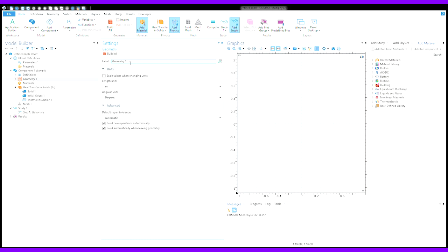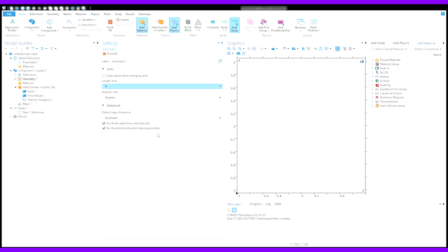We can change the length unit, and that just gives a default length that COMSOL's going to expect. So if we do angstroms, the grid is now in angstroms, so obviously our circle would look huge, so it's not great to use. We could scale out, but it's going to default to zooming in way more than we need. So we're just telling it a baseline. Most of our dimensions are roughly on the order of a meter, plus or minus a few orders of magnitude.